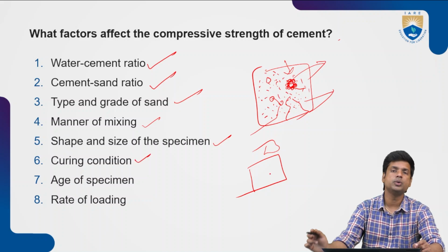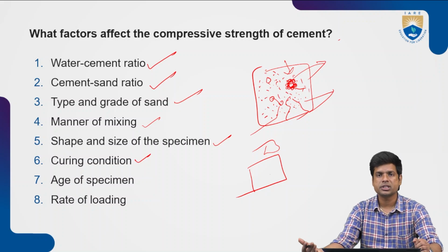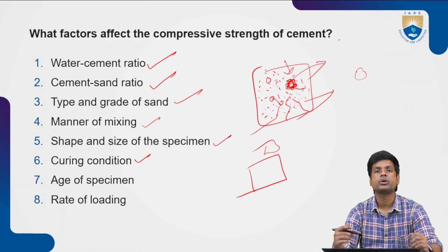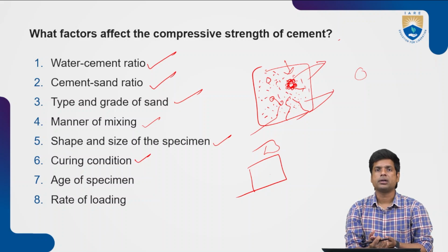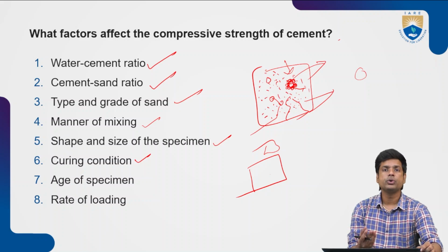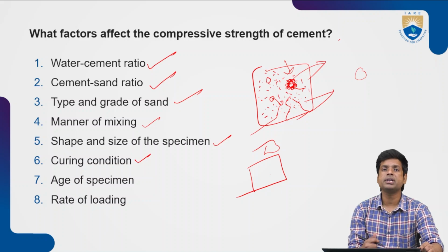So after casting the cubes or whatever the component, curing is also very important. Curing is nothing but the application of moisture to complete the hydration process, right? So whenever the cube is cast, it has to cure properly. We have to apply moisture continuously to complete the hydration process.